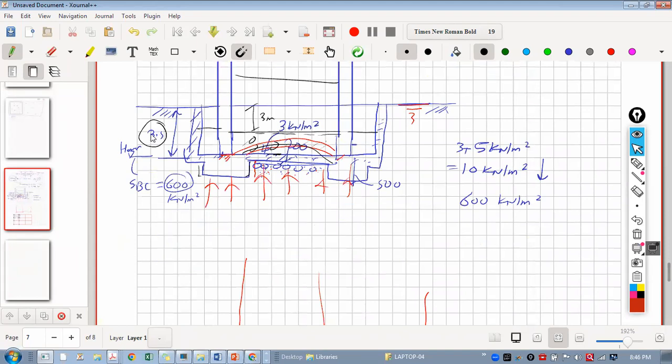Then it is better to design for 3.5 meter uplift pressure instead of having such murum filling or this double work. It will have a little thicker slab and more steel, but fine. The level of the raft will be here, then this will be soft, compact soil here. And then I would not go for this as a choice.